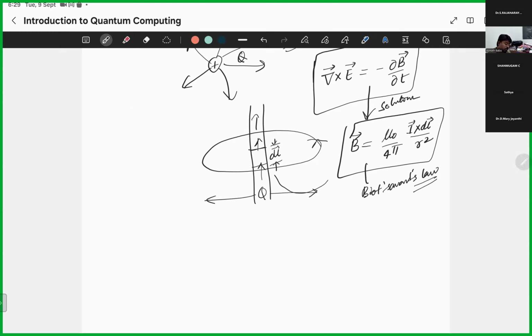So now let's establish there is a current carrying wire. The current is going upwards, so the magnetic field is there around that. Now there is a current, there is a magnetic field. So what you do, you just curl the fingers around, or show the thumb towards the direction of the current, and the curling fingers will give you the magnetic field.